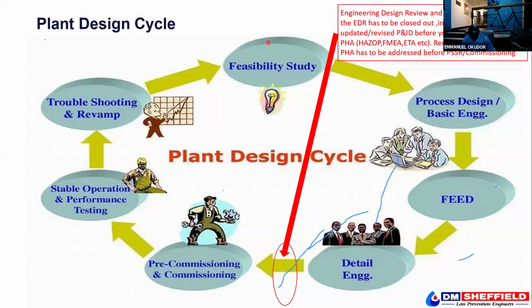such that we did not agree on a pound flange 2,500 that can take 250 bar and somebody changes it to 1,500. I understand. I confirmed that it was true. An Indian guy was blown up recently during pressure testing. And what happened? The flanges, I don't know how true in terms of details, but they used a pound flange that is less than what they were supposed to use.